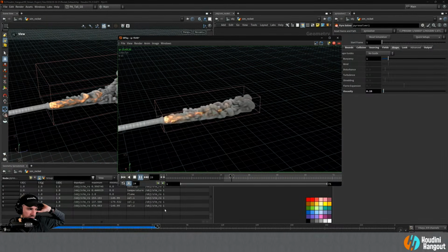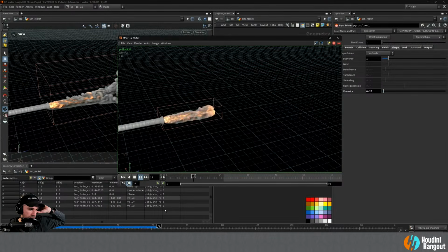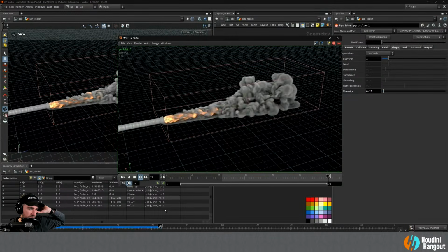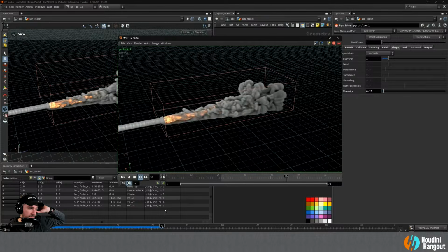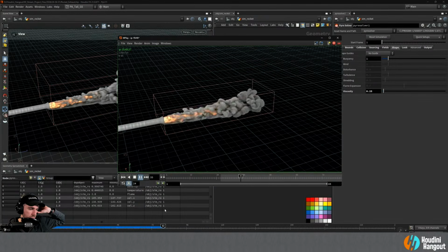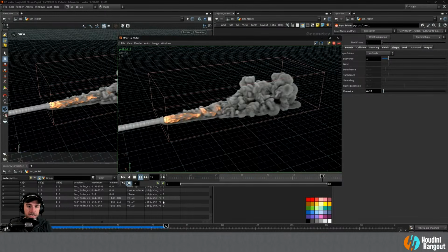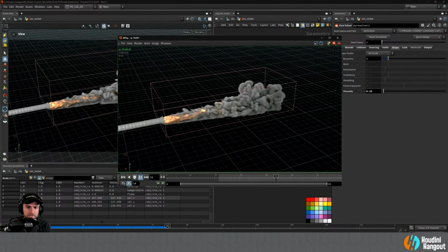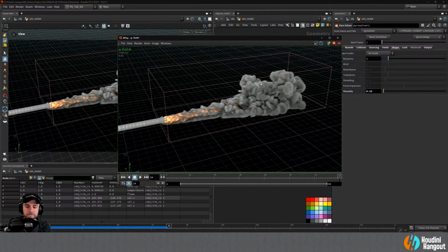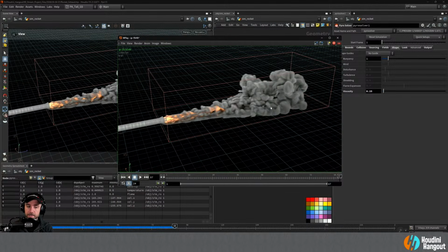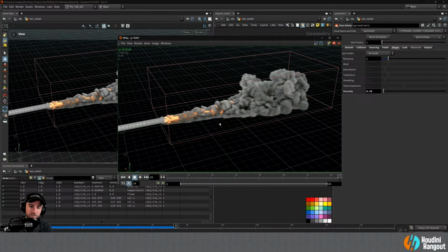Oh, sorry, I didn't see there was a question there. Turbulence, disturbance, and other parameters in the shape tab. Yep, exactly. Yes, those are ways that you can go in and tweak some of these values. So for example, I'll just stop this for a second here. These big shapes, these really soft, pillowy looking shapes, or mushroom cap shapes, those are really affected and kind of removed by using disturbance. And so that's a real key here.